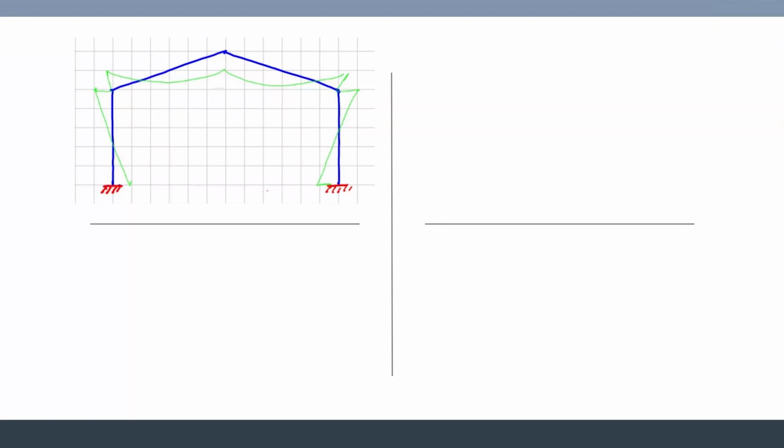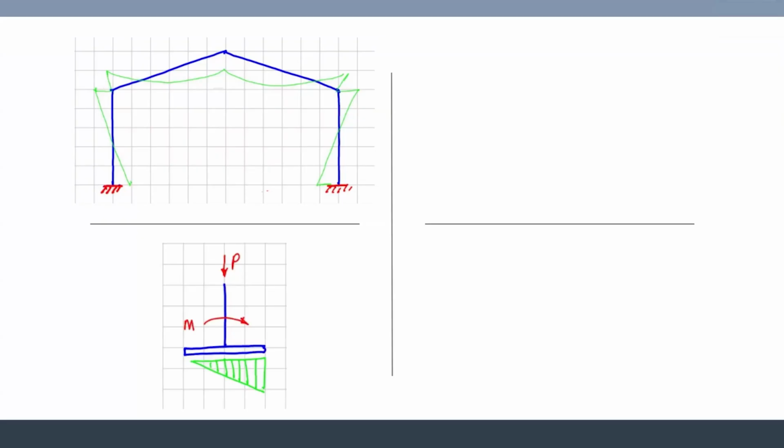And I said, okay, this frame is fixed and I will design it like that. So I started the design and then I came up with the load on the foundation and I came up with a very large moment and very small axial load because the load is small. It's a steel frame, very light, but the moment is very large because it's a portal frame.